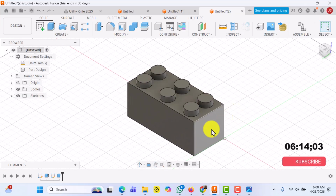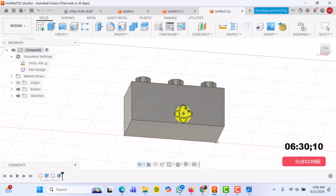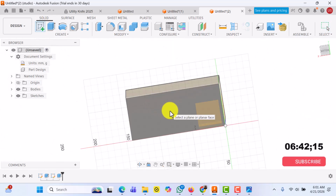All right, now we are just about finishing our Lego brick design. So the final task for this Lego brick design is I want the base of the Lego brick design to have a hollow, the base. So to turn to the base, I'll use orbit. So I'm using orbit now to turn the Lego brick to the bottom. All right. I'll press escape on my keyboard to cancel orbit. Now I want to create a hollow on the base. So I'm going to select the base.